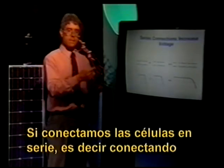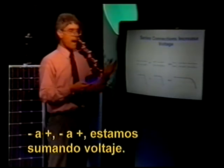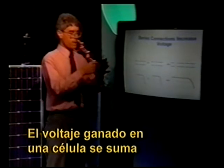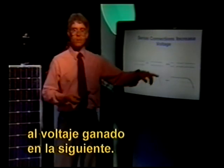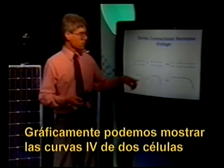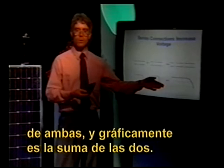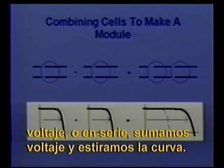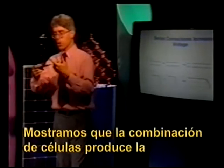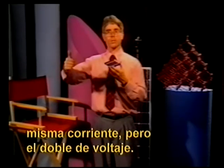If we connect cells together in series, in other words, connecting minus to plus, we're adding up voltage. The voltage gained in one cell is added to the voltage gained in the next. We can graphically show our cells being drawn together in series, and we can show the IV curves of two cells added together to give a composite curve for the combination of the two. And it's just graphically the sum of the two. So notice that when we add cells together voltage-wise, or in series, we add up voltage and we stretch out the curve. We show that the cells combination produces the same current, but double the voltage.